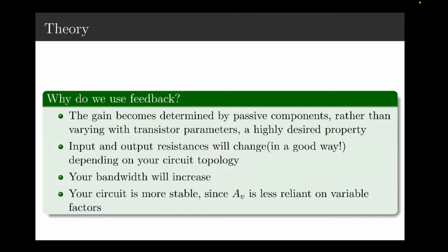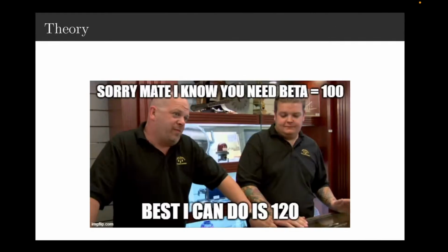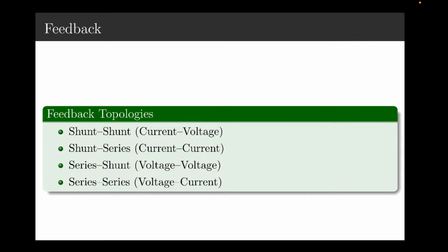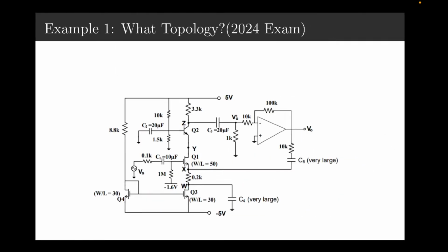So there'd be a voltage divider across this, right? And if your load decreases with the resistance, there's going to be a more even split. But negative feedback says, no, I'm not going to let the voltage change. I'm going to feed back some back into the input. Our voltage stays the same, so our impedance actually improves. Depending on what you have over here, depends on your topology, of course, and whether you're outputting a voltage or a current.